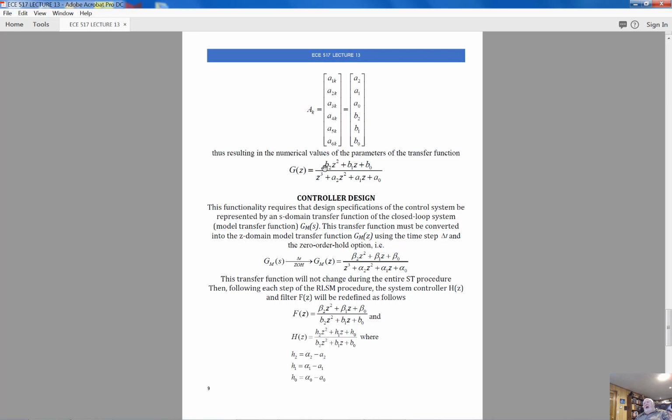So how could a pilot assess the current status of the airplane? For example, by special software that would analyze time-dependent estimates of the unknown parameters and provide some critical information to the pilot. So I would say that in addition to control benefits, the explicit self-tuning enables us to have some diagnostic system capabilities that are very important.